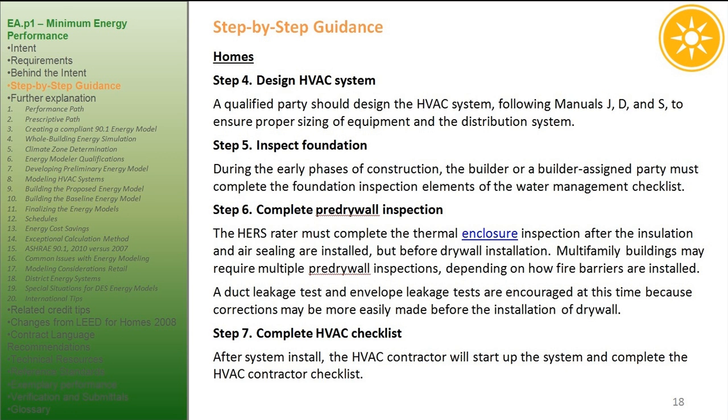Step 6. Complete pre-drywall inspection. The HERS rater must complete the thermal enclosure inspection after the insulation and air sealing are installed, but before drywall installation. Multifamily buildings may require multiple pre-drywall inspections, depending on how fire barriers are installed. A duct leakage test and envelope leakage tests are encouraged at this time because corrections may be more easily made before the installation of drywall.